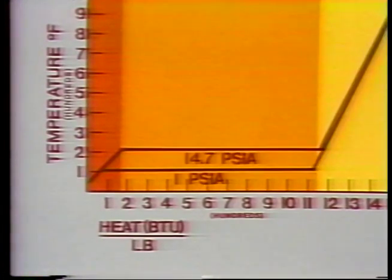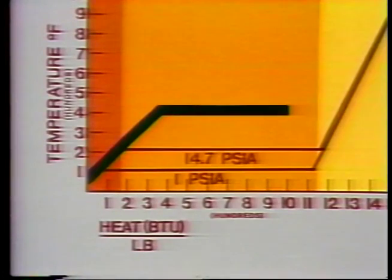As you have probably noted, the process line for both 14.7 PSIA and 1 PSIA are quite similar. Let's look at the process line for a higher pressure. This time, the pressure is 200 PSIA. The line in the subcooled region rises as before, with the exception that boiling occurs at a higher temperature. During boiling, the line moves in this direction, and in the superheated region, the line moves in this direction.